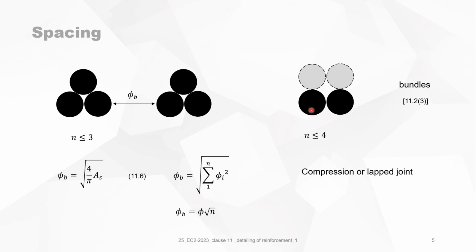For instance, in this drawing, you will see a continuous bundle with 2 bars, and it's overlapping with another bundle of 2 bars. So in this lap length, you can have a maximum of 4 bundled bars. Otherwise, it should always be smaller than 4. When there is compression, you can also use a maximum of 4 instead of 3.